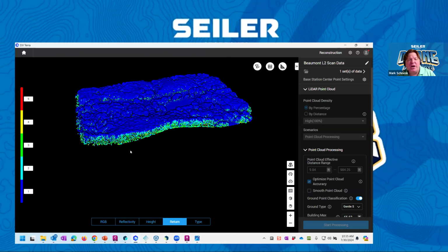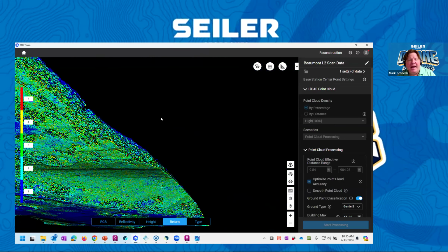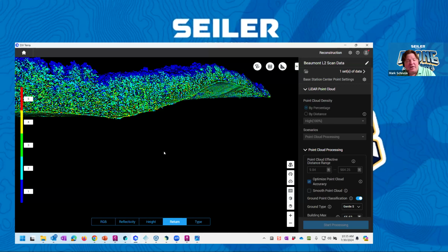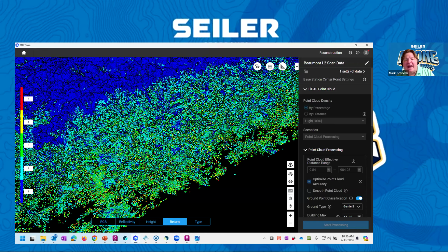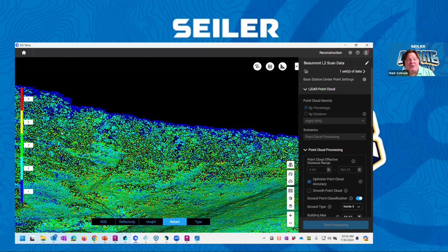And you can see we talk about LiDAR having multiple returns. As the LiDAR light from the drone exits the vehicle, it's going to diverge to a small cone like this. And as it bounces off different objects it detects, that light comes back as a fractional bounce back. So one single light beam can get multiple objects down. Those are called returns. Certain LiDAR, like the DJI L1, can track up to 3 returns. Certain ones like the TrueView 660 and the DJI L2 can get up to 5 returns. And there's a lot of software that says, hey, when I'm digging for ground, we're going to look at those last returns and prioritize those over other returns.